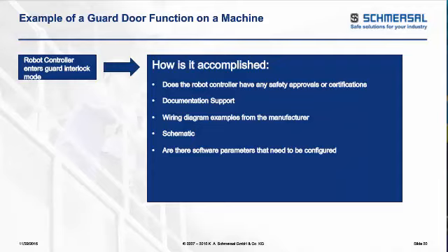Where a robot has the safety approvals, it has the redundancies and checks inside the controller. When you have an existing controller that doesn't have that, you have to figure out how to safely shut down that robot controller. There may be several different ways of doing it. It may be breaking the enabling signal and the motor power. There's not one catch-all solution that covers all of those, but the point of this webinar is you really need to take a look at what needs to be shut down and how you're truly accomplishing that safe shutdown of, in this case, the robot controller.